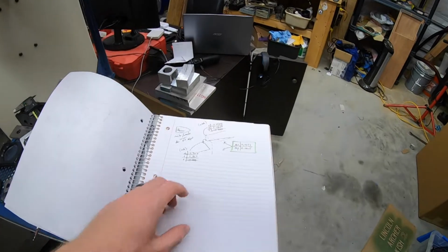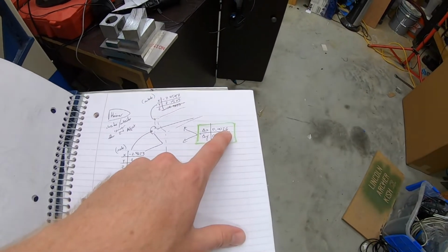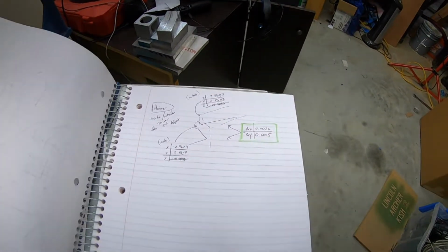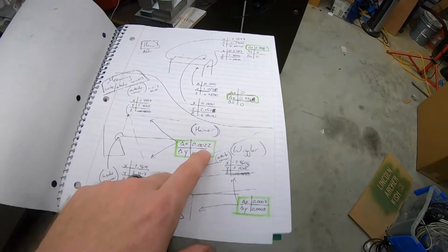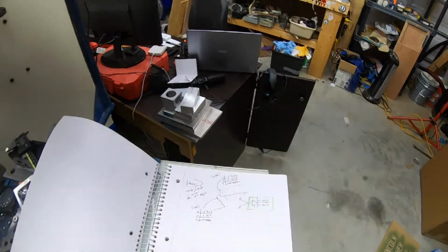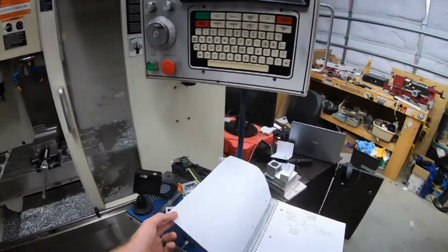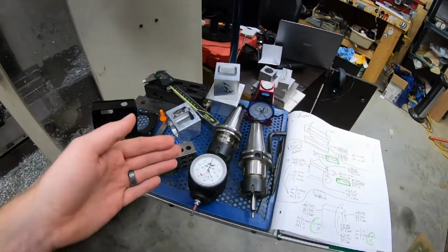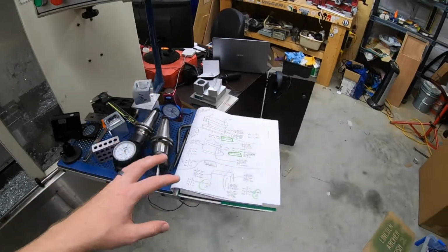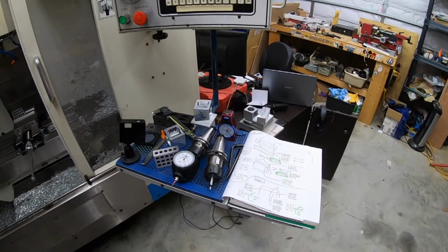Tried to adjust it one more time, and I got a little bit worse. This is 2 thou 6/10, and then this is 1.5 thou, whereas previously I had just over 2 thou, just over 1 thou. So here's where I again, looking at forums, I actually emailed Heimer and said, what can I do? Because I saw that people try to repair theirs. Again, I'll also put all the forums and links that I found down in the description. Hopefully, maybe it'll help someone else.